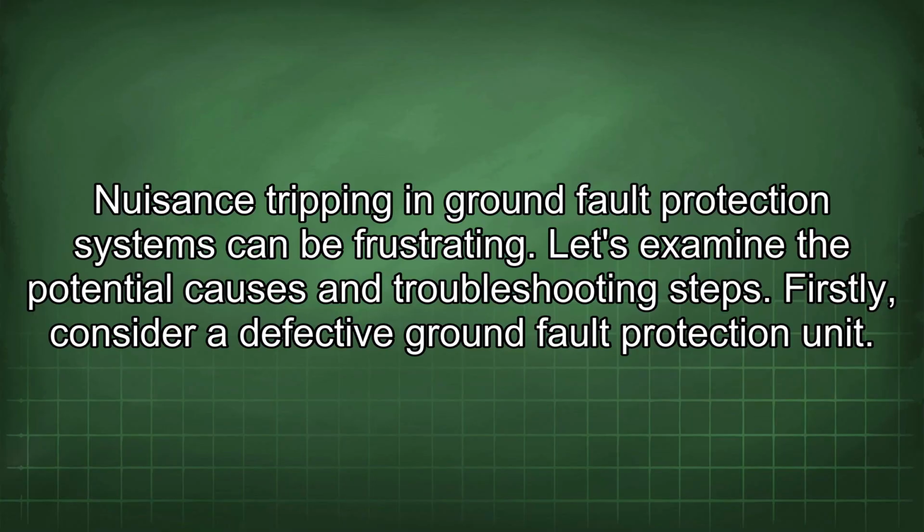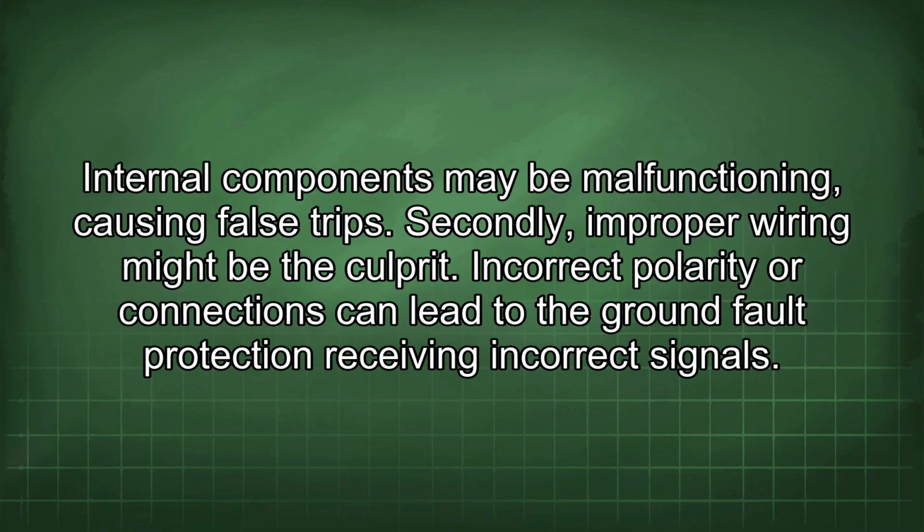Nuisance tripping in ground fault protection systems can be frustrating. Let's examine the potential causes and troubleshooting steps. Firstly, consider a defective ground fault protection unit. Internal components may be malfunctioning, causing false trips.